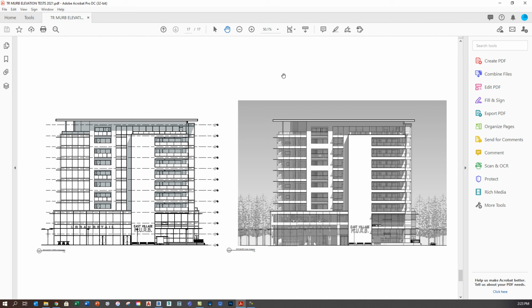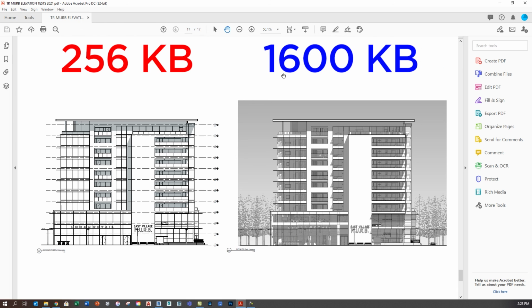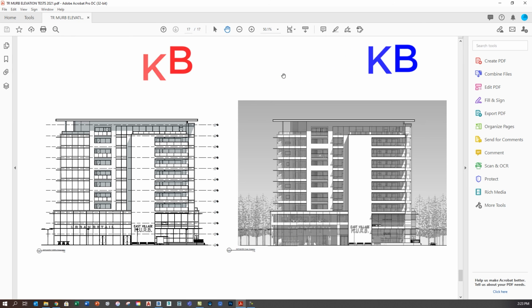What's important to note about these two is that there's going to be a really significant difference in the size of the files. So over on the left, we're going to have a much smaller file size because we've preserved that vector quality. And over on the right, even though it's maybe a little bit more graphically significant and punchy, we've actually generated a much larger file. On a one-off, that's probably not going to matter, but if you can imagine a full set of sheets, that's going to be a factor maybe in what decision we make and which one of those graphic strategies we pursue. So keep that in mind. There might be a lot of times where you want to keep it simple like on the left and go with the smaller file size.